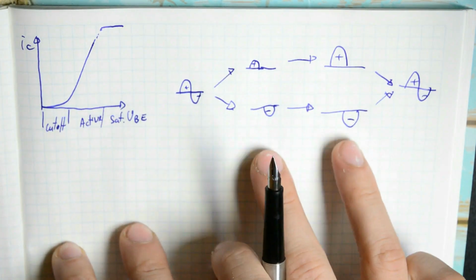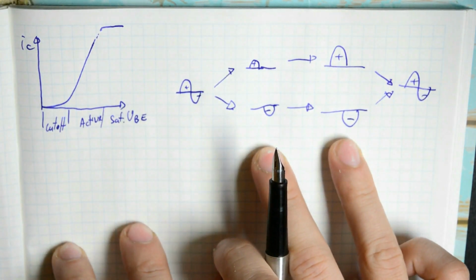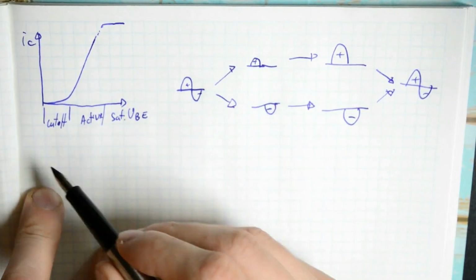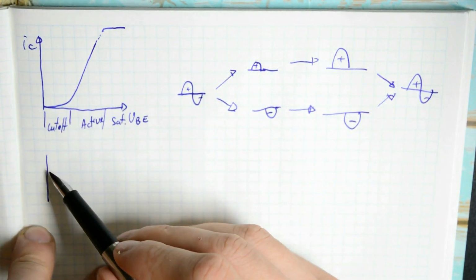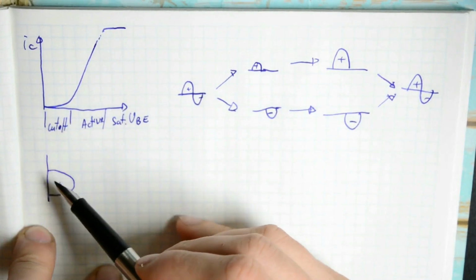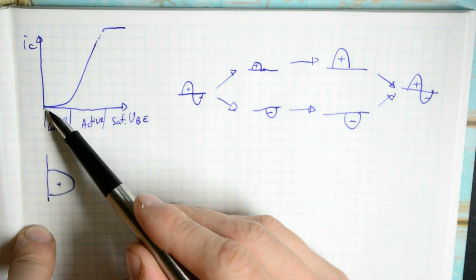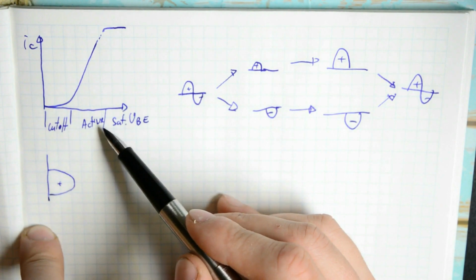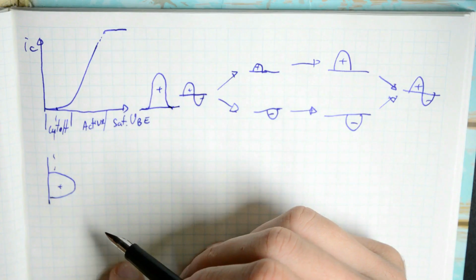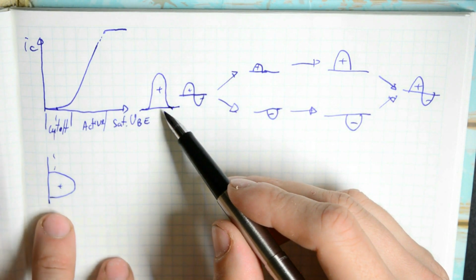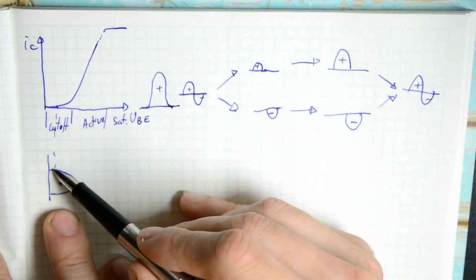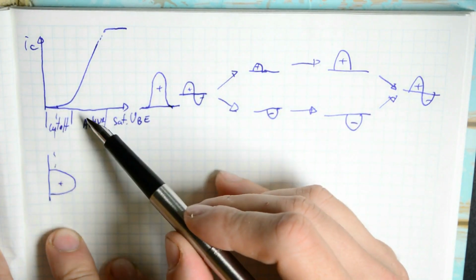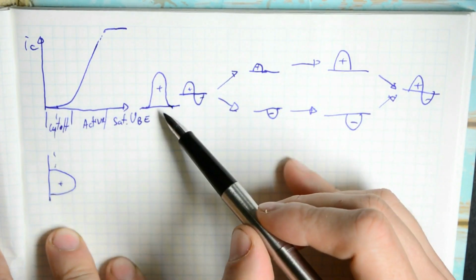Well, it has to do with this part, the amplification stage. Basically, you take your half signal and amplify it directly with your transistor. That means that when you have very small signals, your output signal is not amplified at all. Only when the signal is large enough does it reach the active region of the transistor and become amplified. So your output signal will be just like your input signal, only with the beginning of it chopped off. So the voltage needed to actually put the transistor into the active stage will not be seen at the output.